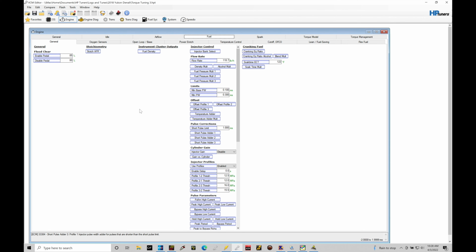Well, we don't want to jump into the mass airflow table and scale down the air mass reporting. We don't want to jump into the speed density tables and scale down the estimated air mass reporting. If we do that, that will affect what's going on with the cylinder air mass calculation and then also affect the torque calculations. So everything's going to get all out of whack when we do that. We want to try to keep the engine control module in its best calibration.